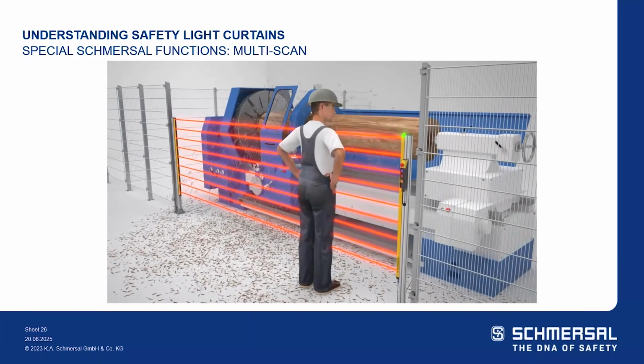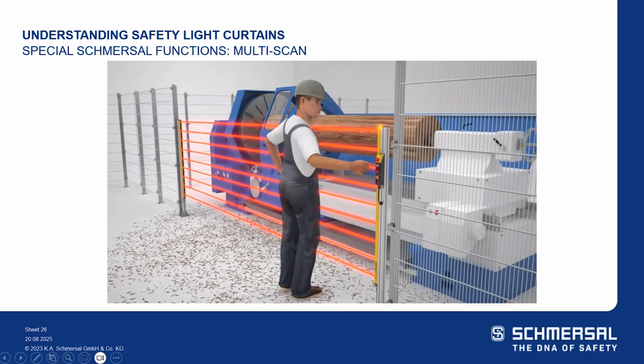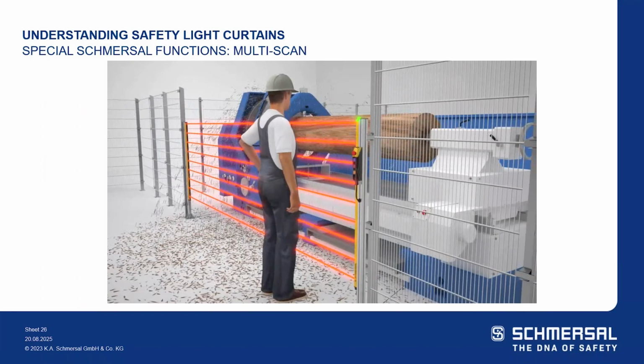But again, here comes Johnny-come-lately. It will detect him leaning in, but did not pick up and detect the material being created as they're cutting up this piece of timber, this piece of log. So this is going to allow you to increase machine productivity and availability by limiting the number of false stops associated with temporary disturbances. However, the light curtain will still prevent your operator from passing into the hazardous area.